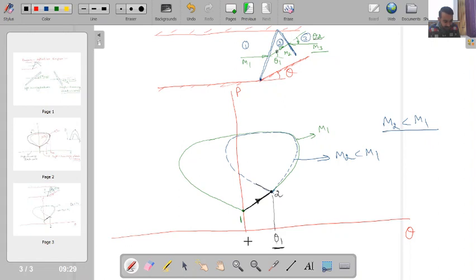If I move back theta 2, you can see over here, if this angle is theta 1, this angle is theta 2, because these two lines are parallel. So in this situation theta 1 is equal to theta 2 is equal to theta. If I move theta 2 in the backward direction, I will reach this point. Once again my flow has become horizontal over here, which you can also see. So this is my point number 3, and this completes the process 2 to 3.